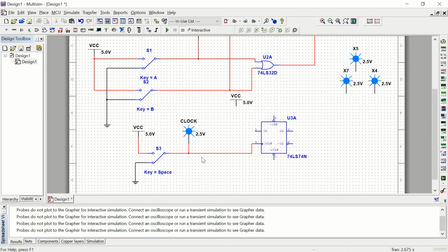All right, where does this VCC go? This VCC goes to 2 different places. It goes right here, and that is your reset. And it's active low. So we haven't talked about this, but those little circles mean that it's going to reset when it's low. And then it's also going to come down here to the clear, or preset, sorry. And then it's going to clear when it's low. So by tying those to a high voltage from your power supply, it means it's never going to clear itself. So you're taking away the capability of that clearing itself.